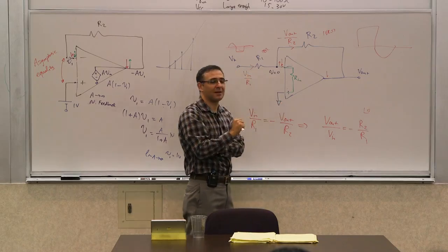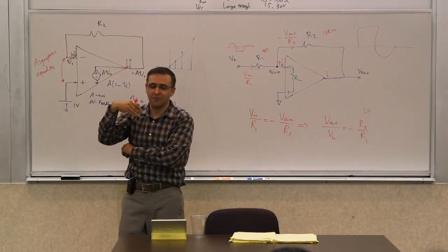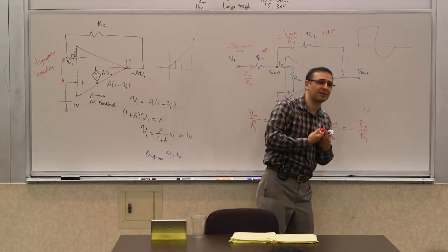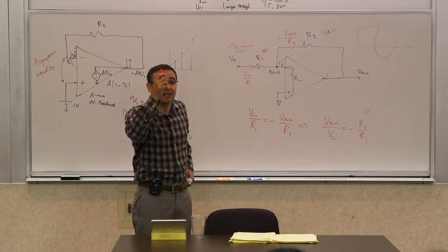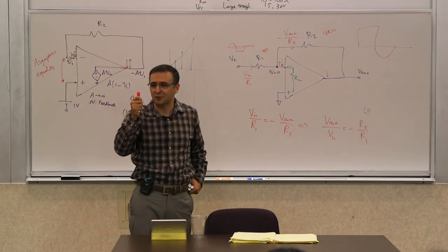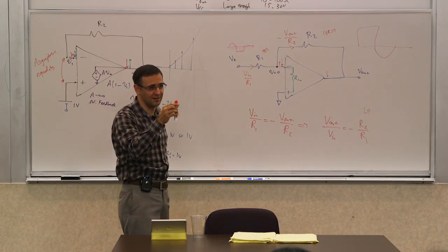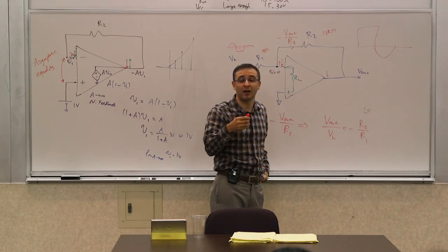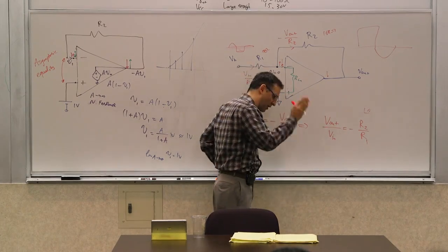There's something even more fundamental to that. See, controlling the gain of an active device, because it's coming from a pretty complex solid-state device that has a lot of interesting dependencies on temperatures and other parameters, controlling it and getting something fixed and controllable is hard. It's hard to make an amplifier. It's doable, but it's challenging to make an amplifier which has a very large gain and is very well controlled. You can say, my gain is exactly 100,000.